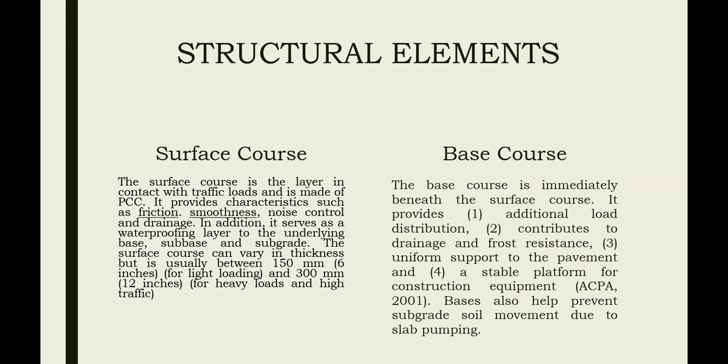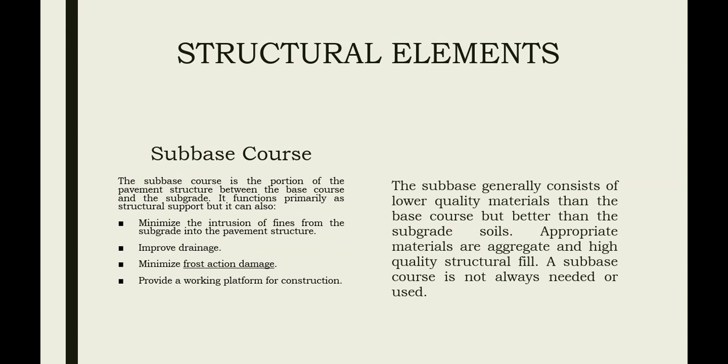So what is base course? The base course is immediately beneath the sub-base course. It provides: 1. Additional load distribution, 2. Contributes to drainage and frost resistance, 3. Uniform support to the pavement, and 4. A stable platform for construction equipment. Bases also help prevent subgrade soil movement due to slab pumping.